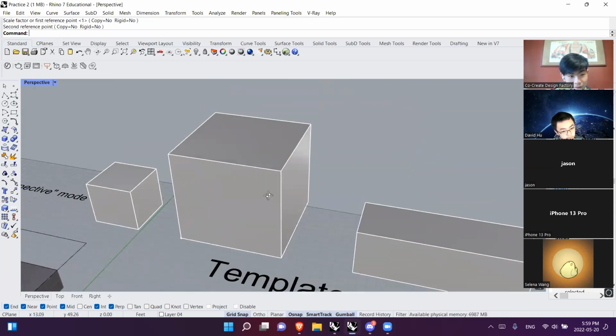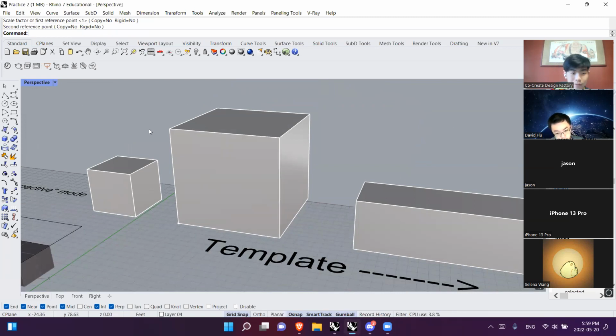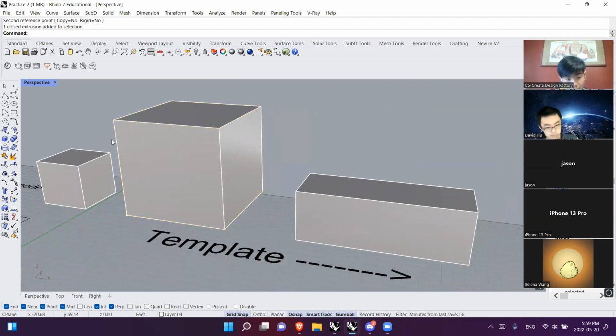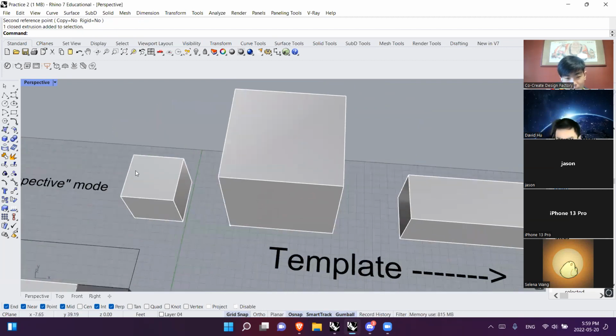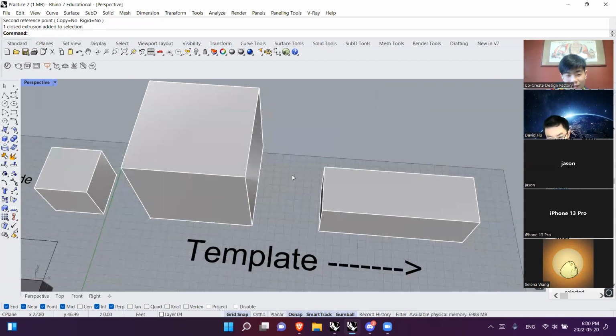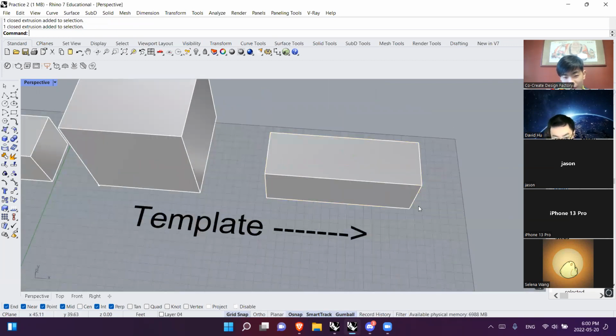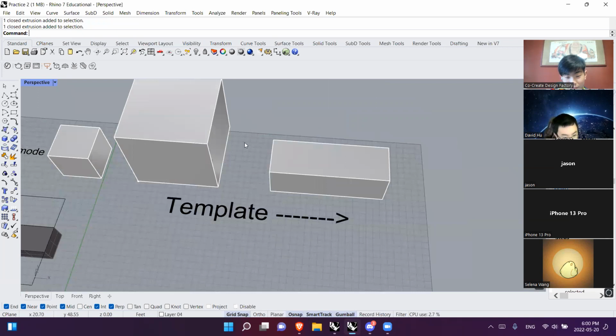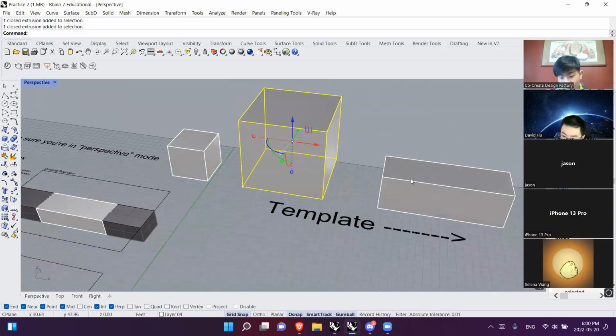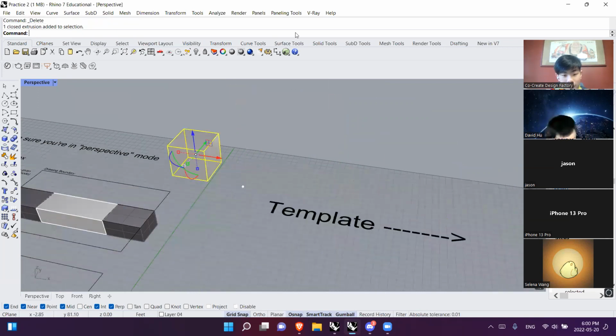For now, just remember scale without anything, just simply scale, and scale 1D. Scale is the one that keeps the proportions, makes the object look the same, and doesn't distort anything. And then scale 1D is the one that changes your proportions. Okay, hopefully that answers Rachel's questions.